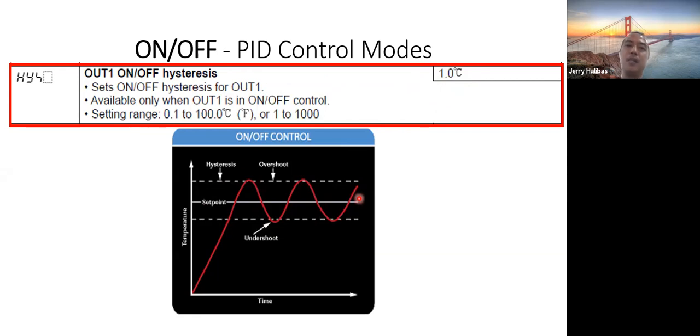By the way, I forgot: the on and off control mode, if we apply it to a flat iron or plansa, is equivalent to what is called a thermostat. Your flat iron is not proportional in increasing or decreasing heat. It is on and off, using a thermostat. The same goes for heaters and water heaters, much more so air conditioning systems. They use a thermostat.